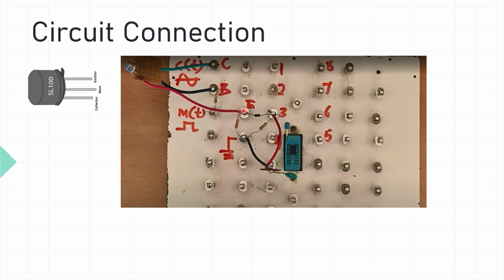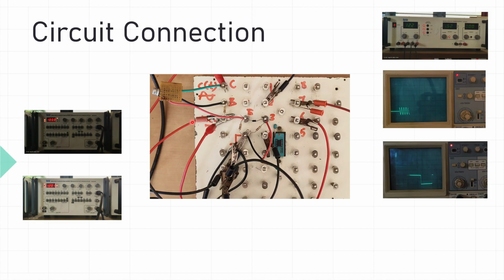In the second part, you are connecting diode directly to pin number 3 of op amp. Across that, you are connecting the capacitor and resistor 10K, and it is connected to common ground here. In order to power up the op amp, you are connecting fourth pin to minus VEE and seventh pin to plus VCC, and you are taking the output at pin 6 by connecting a V reference to pin number 2 of op amp as shown. So this is the circuit connection.